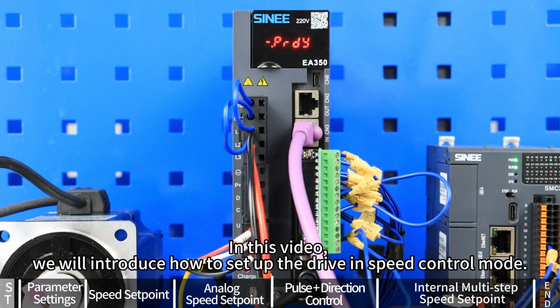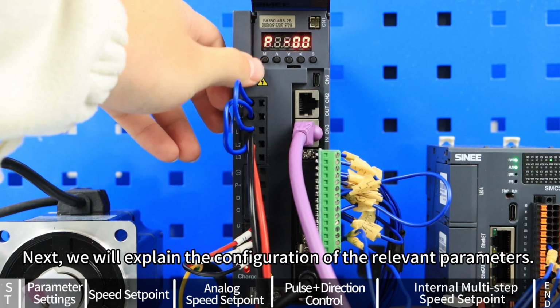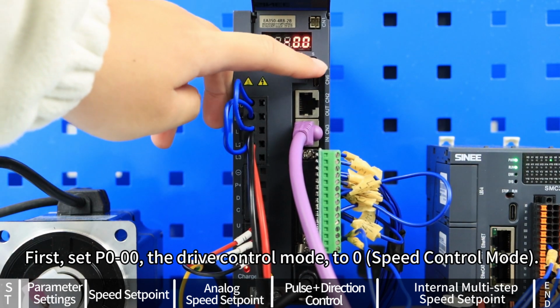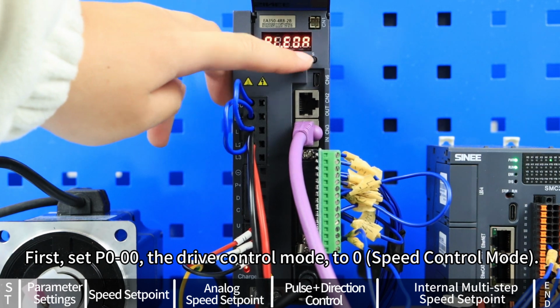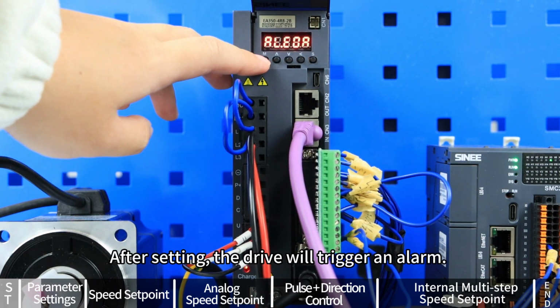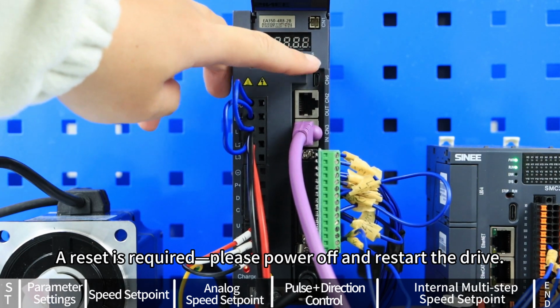In this video, we will introduce how to set up the drive in speed control mode. Next, we will explain the configuration of the relevant parameters. First, set P000, the drive control mode, to 0, speed control mode. After setting, the drive will trigger an alarm. A reset is required. Please power off and restart the drive.